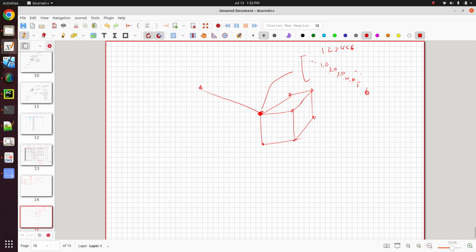But for this other node, where it's only connected to the 3D element, here we continue on the stiffness matrix, and here again it starts again. 1, 2, and 3 for the translation degrees of freedom, but then the other elements are all zeros for the rotations.